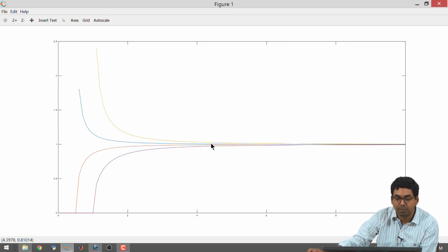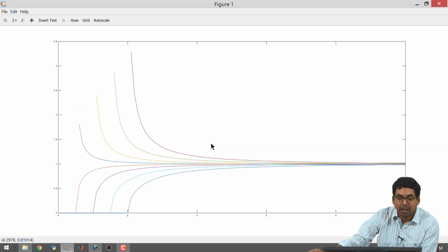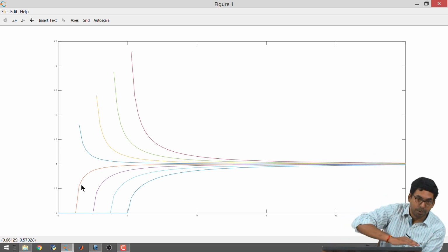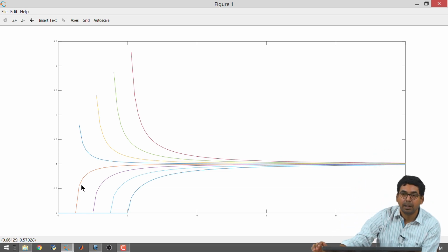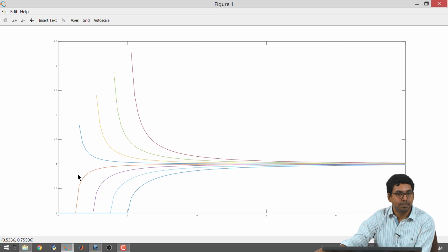So, I will just make a click for the next higher mode, right, and it keeps going. So, I know that this plot corresponds to the group velocities because it is asymptotically approaching 1 from 0, okay, and the other plot is going to be for the phase velocity. Okay. So, this is how the phase and the group velocities would look like for your parallel plate waveguide, all right. So, you are having some curves that tell you that the velocity is changing with the operating frequency.